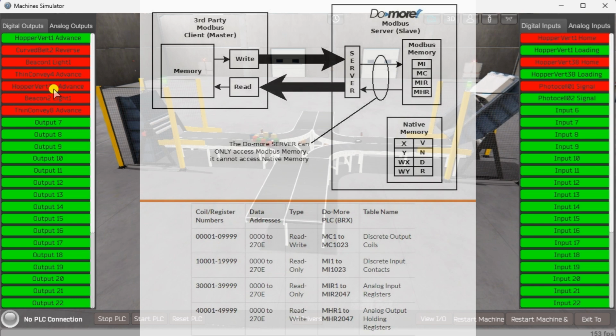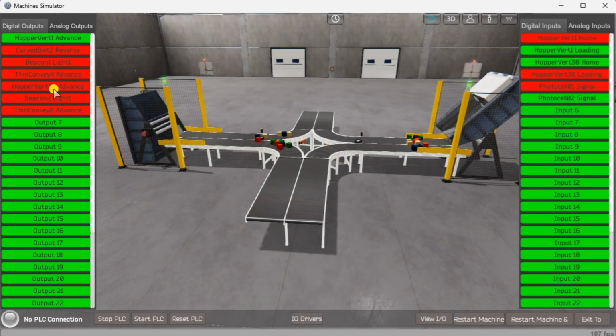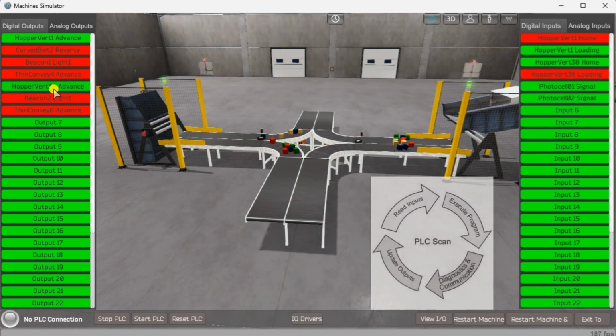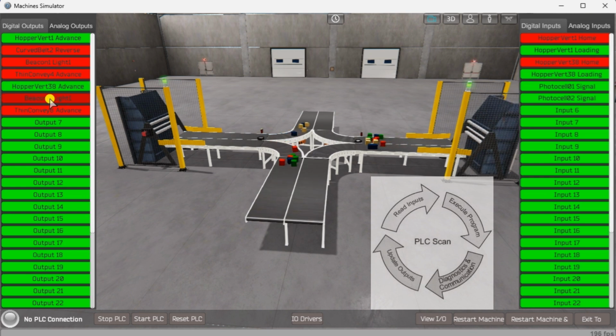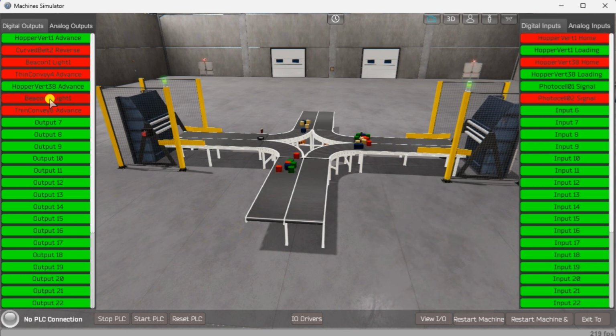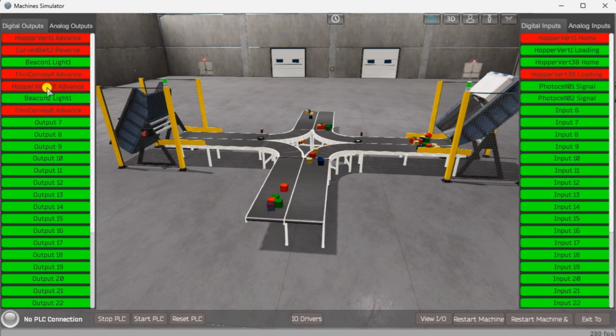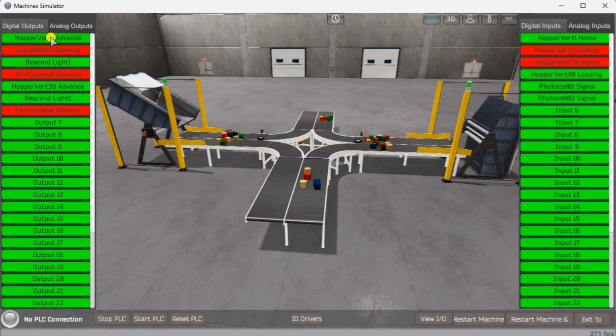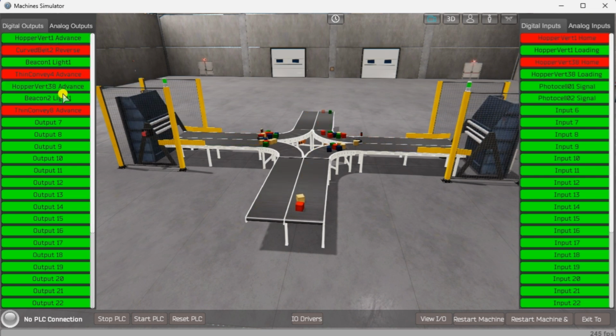It is important to note that PLC programs operate cyclically, meaning they continuously read the inputs and set the outputs. This ensures that the program is responsive to changes in the system and can adapt accordingly. By understanding the inputs and outputs and their relationship to the overall system, you can develop a logical sequence of operation for the Box Dumper PLC program.